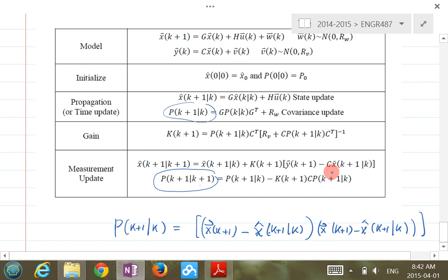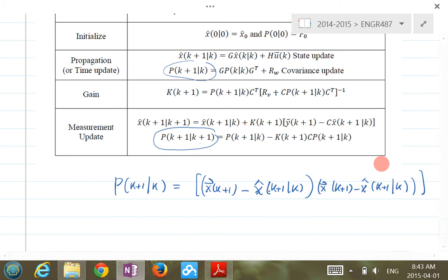Basically, it's like your pole placement. So you have a gain k. What do you use that k for? That k is used to multiply the feedback x of k, right? In the observer design, it's the same idea. You have an observer gain k, then you multiply it by the difference between the observed value. So if we had high measurement noise, like our sensor had high noise, we want to boost our gain, right? Exactly.